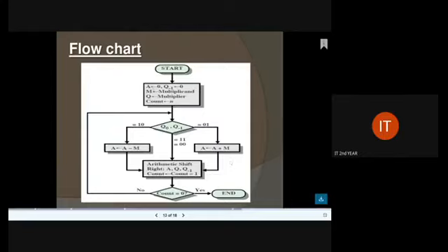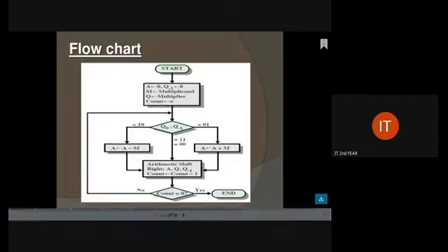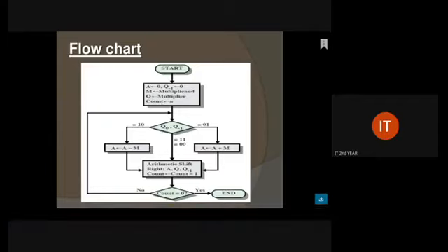So initially we will be assigning A as 0, that is accumulator with the initial value of 0. Next Q minus 1, so this value will also be 0. Along with that, M and Q we will be generating. M is the multiplicand and Q is the multiplier. Next one is count. It acts as a counter for generating each and every iteration.